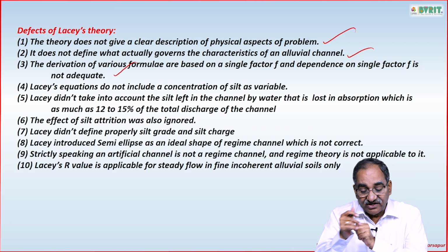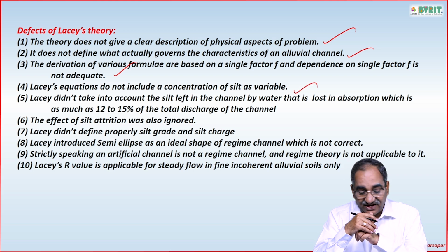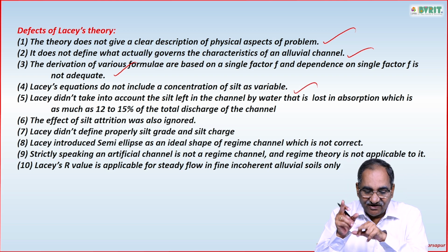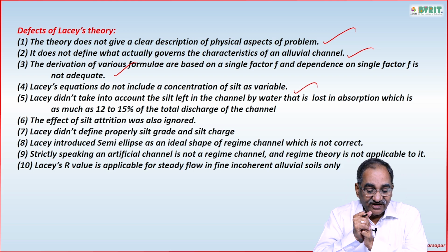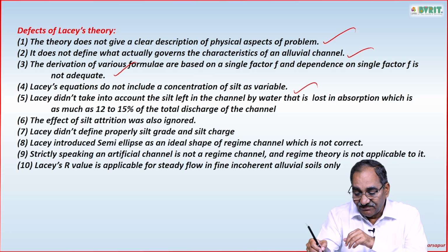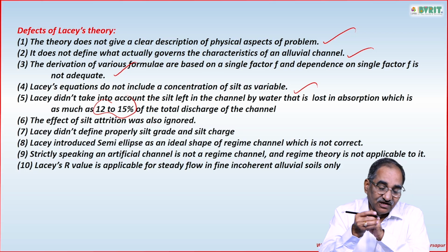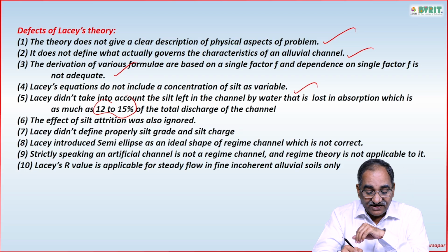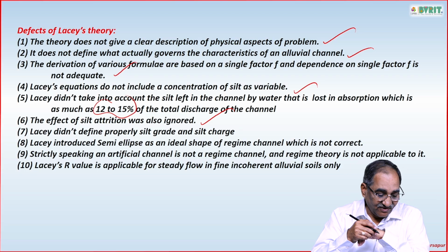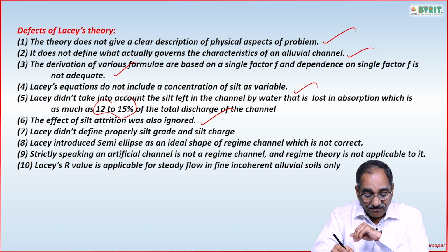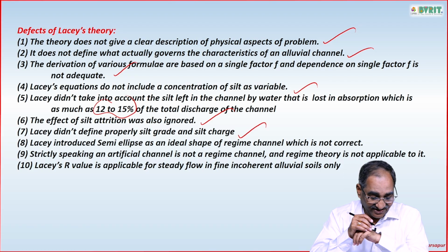Lacey's equations do not include concentration of silt as a variable because he has taken only F. Lacey did not take into account the silt left in the channel by water that is lost in absorption, which is almost 12 to 15%. The effect of silt attrition is ignored. Lacey did not define properly the silt grade and silt charge.